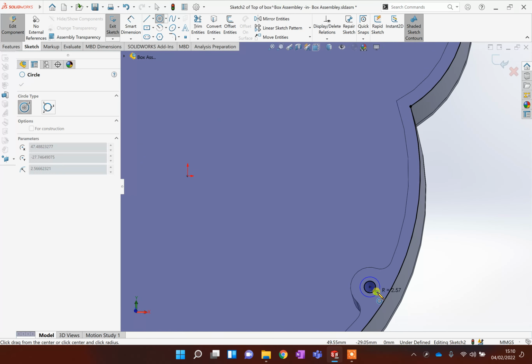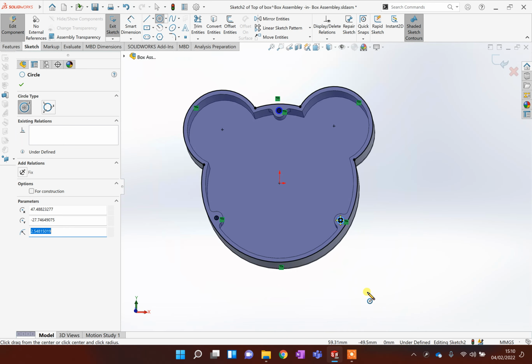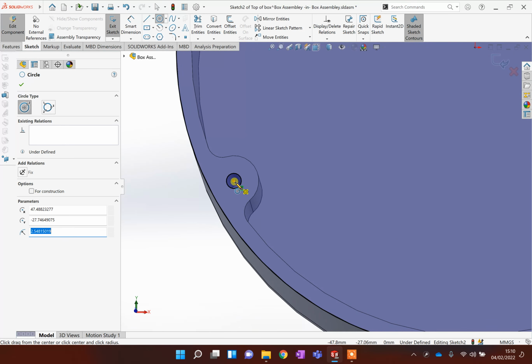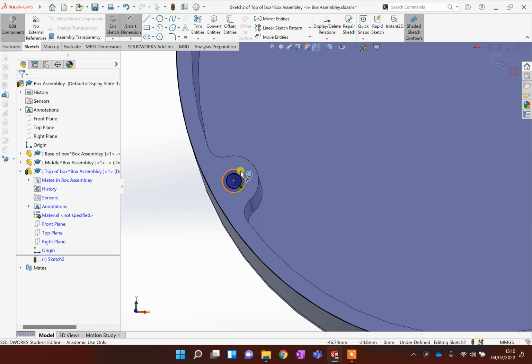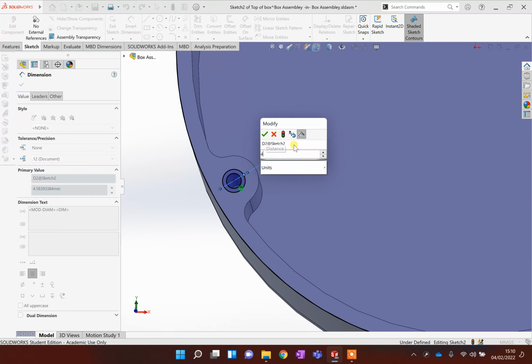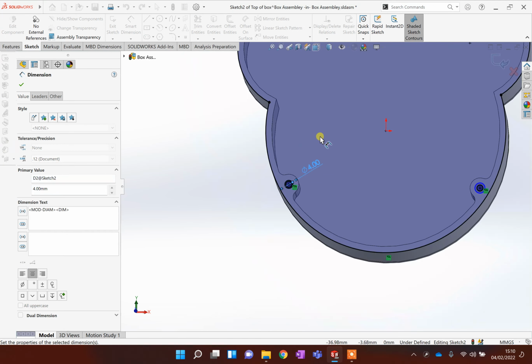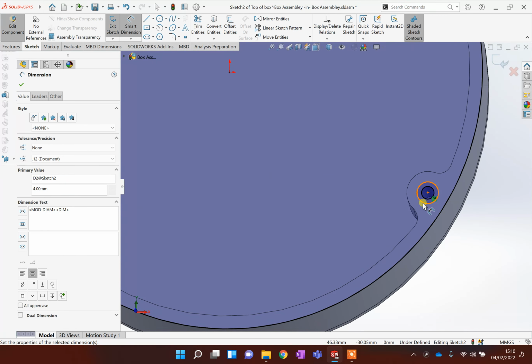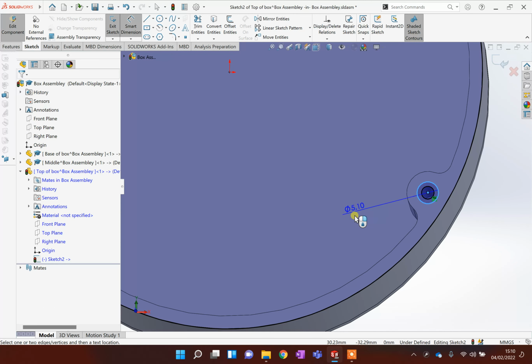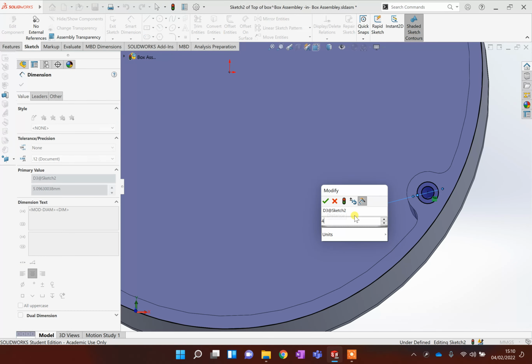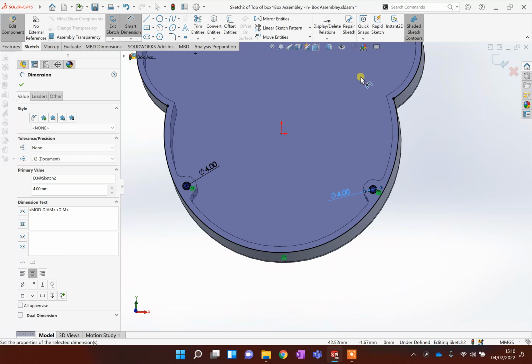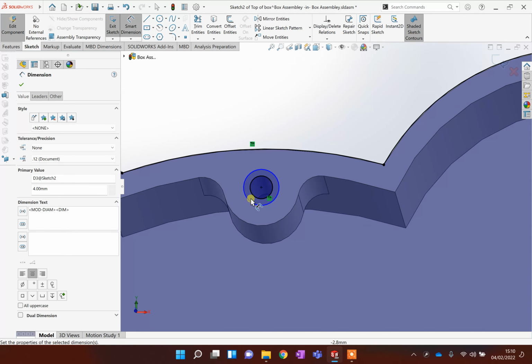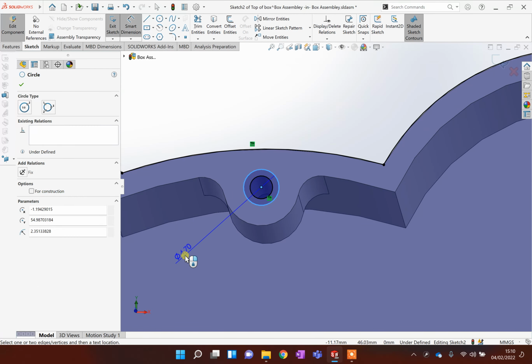1. So click in the middle this time because you want it to be joined to it. 2, 3, and we want to make these holes 4 millimeters. Okay, you'll see why when you build this thing, but basically the holes going through the lid are there so that the screw fits through it and spins but doesn't grip the lid. And the bit below it, the sandwich panel if you like, that is a smaller hole because we want the screw to bite into it. It'll all make sense when you got it in your hands, just trust me on this one.